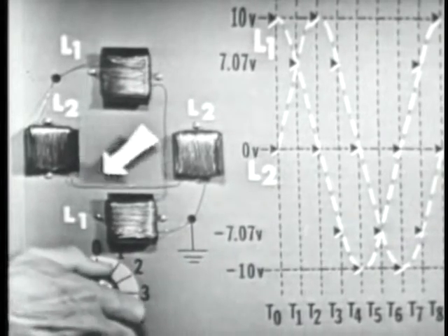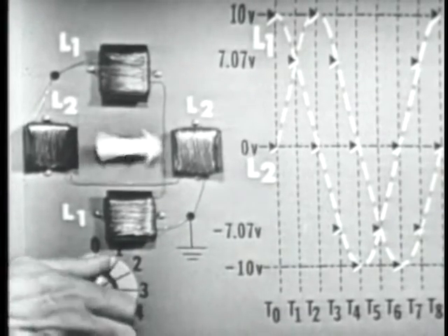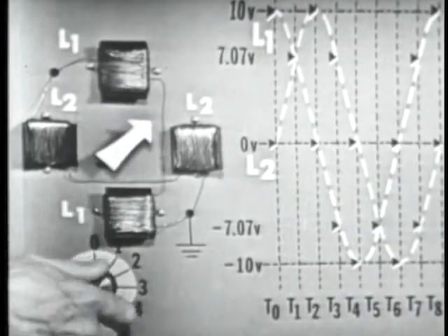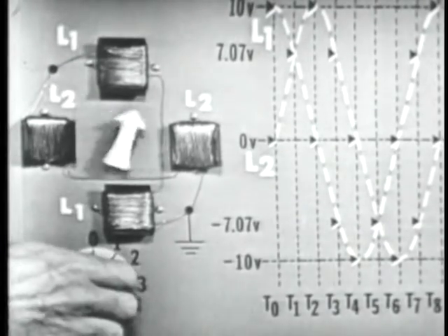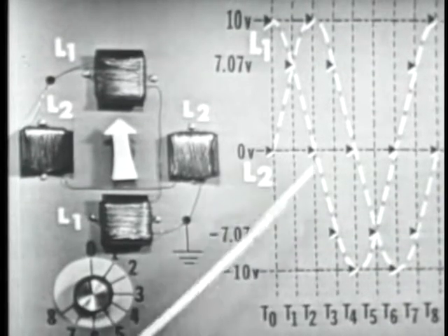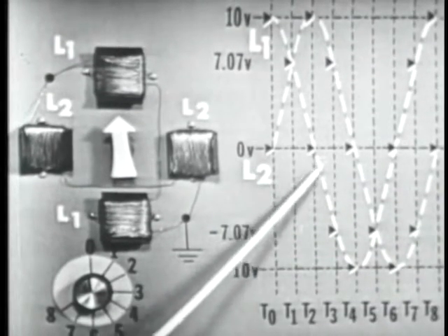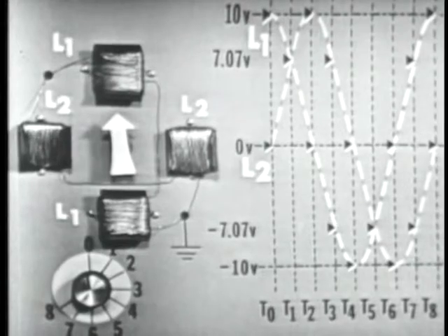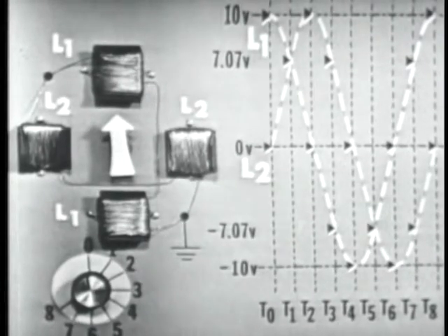It'll work at other phase differences. In fact, any phase difference other than 0 or 180 will give you a rotating magnetic field. But as you said, the most efficient one is 90 degrees phase difference, and that's the one that's probably most commonly used. Right. Now, I'll take item 4. All right. Help us out.